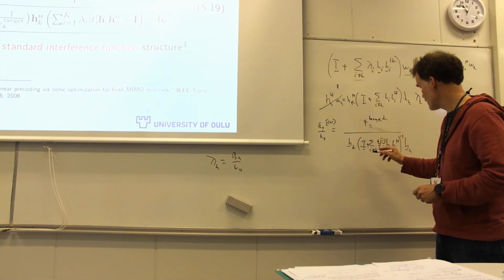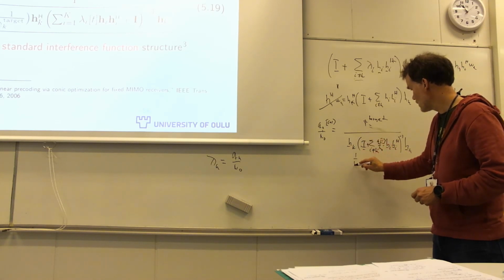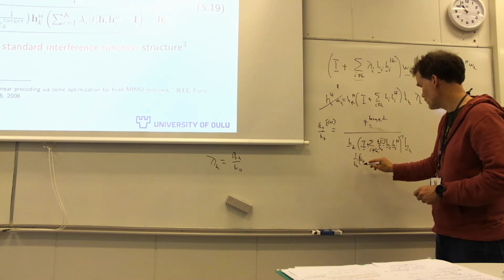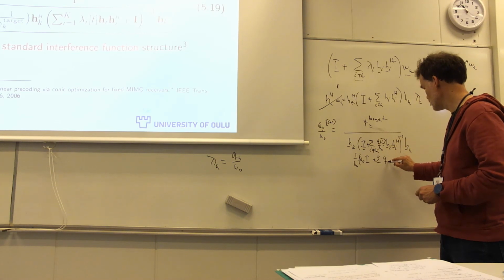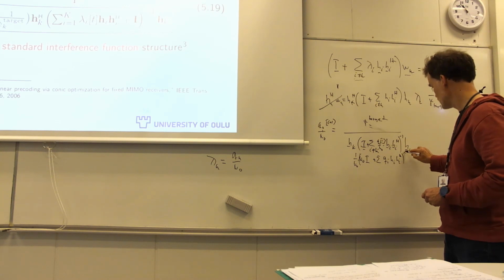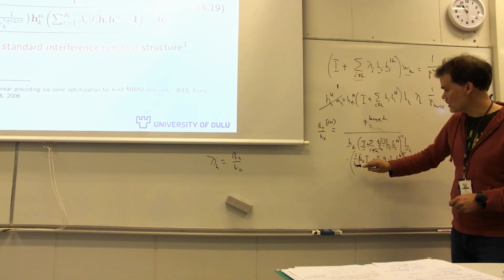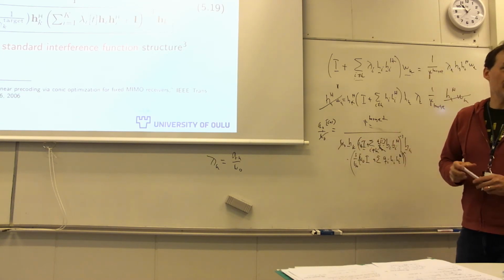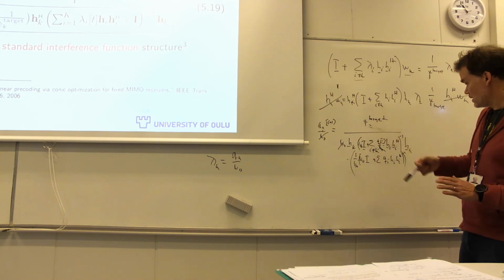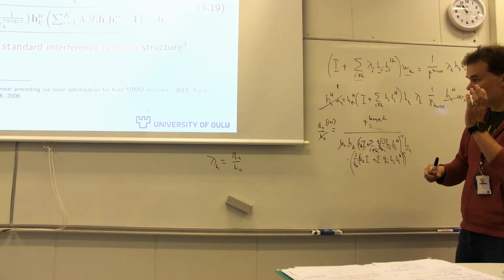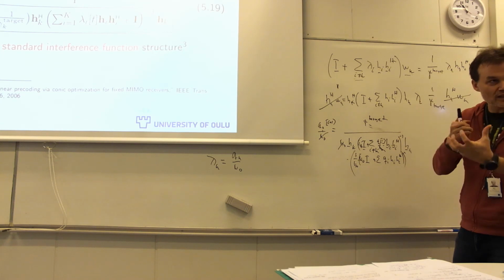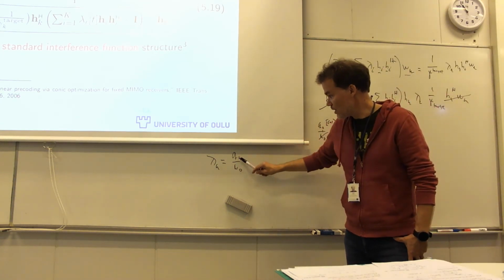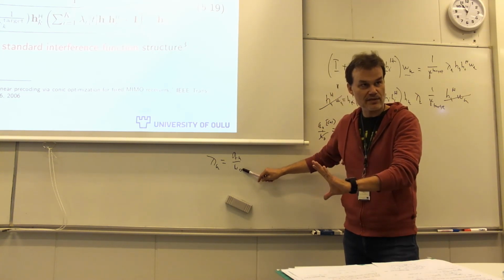Now we can take 1 over n0 out. We have identity here plus qi, hi addition. And then this 1 over n0 goes in front, right? Cancel. And this cancels. So we have equivalence here. So this is a nice interpretation that now this dual uplink downlink duality, the power duality, and the Lagrange duality are fully connected, right? By assigning lambda k to be qk over n0, we have the exact match, right?